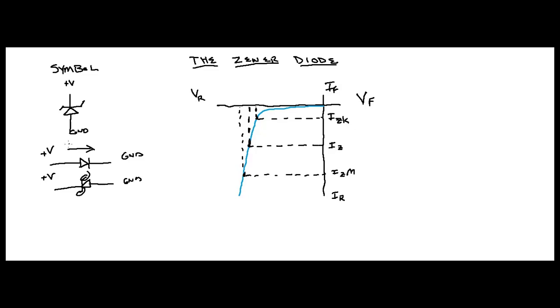The other thing I wanted to emphasize is that it's operated in reverse bias, all right? So if you recall with the diode generally, if this is your I axis right here, and that's forward biased, and then this is your forward bias of your voltage, you would come through here until it reached about 0.7 volts, and then it would just shoot right up, right?